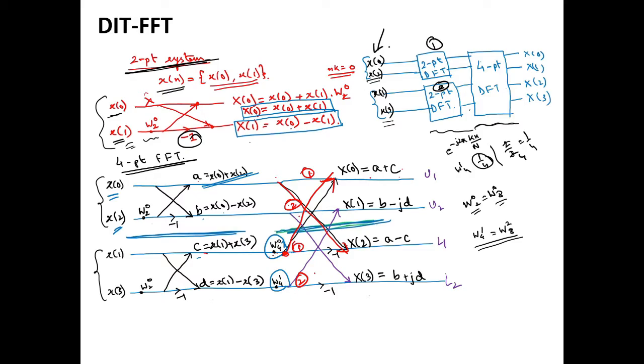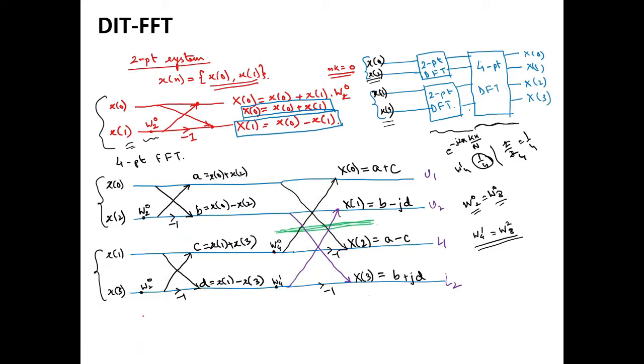Now in the next line, from point 2 to point 2, the twiddle factor you will be getting is W14. Then the signal will cross from line 2 to line 2 over here, and vice versa from top to bottom. Now over here what you are getting, x1 equals, we got B over here, B, then what is W14? W14 is nothing but minus j, so minus j multiplied by D. Similarly, at the bottom half you get B minus of minus jD, so it becomes B plus jD. Any doubt? It is very simple. Anyone having any doubt, please ask me.